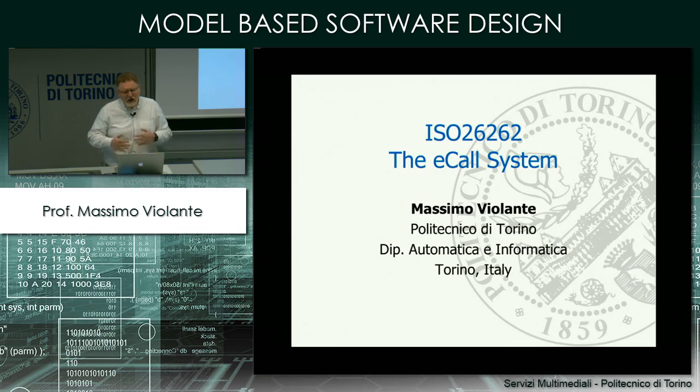So the example that I want to propose to you has the same format that we have seen a couple of lectures ago. So I will introduce the item, then you will have time on your own to think about the different aspects of the concept phase of the ISO 26262. So you will have to analyze the item, defining the elements, the operational situations, and the hazards. Then you have to do the hazard analysis and risk assessment, as we have learned, and eventually you have to define the safety goals, the functional safety concepts, and the safe state. This is nothing new. This is something that we already have seen together, but as I said, it is worth that you put this on your own at work.